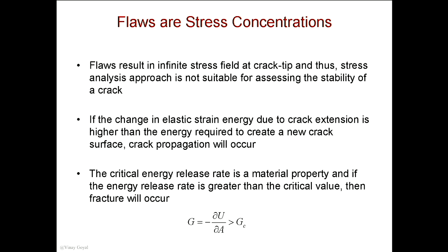So did I have loss of strain energy because of this? So when there's a crack that forms in the structure, there's creation of new surfaces. And this creation of new surfaces causes a loss in strain energy, okay? And that loss in strain energy is called the energy release rate, okay?